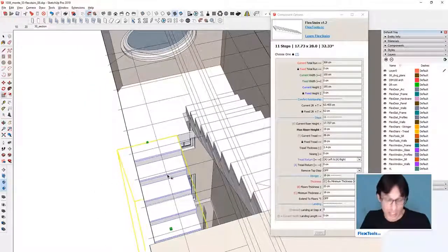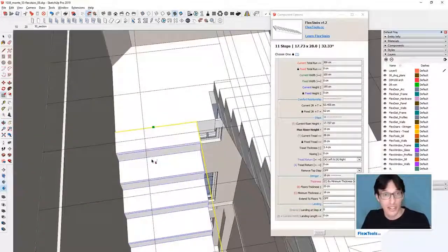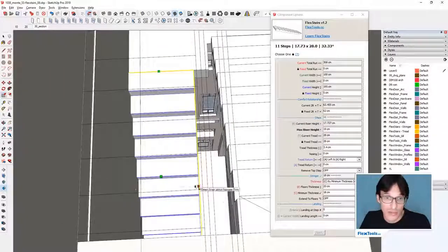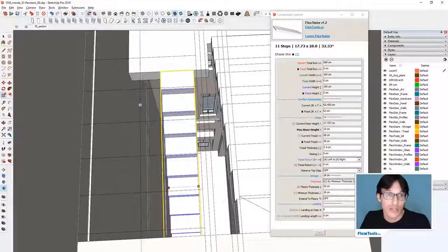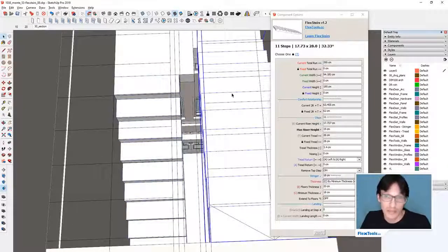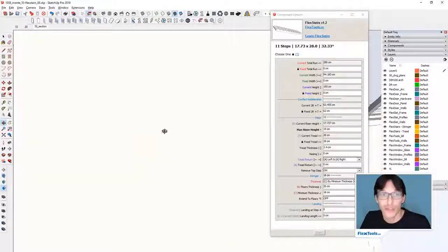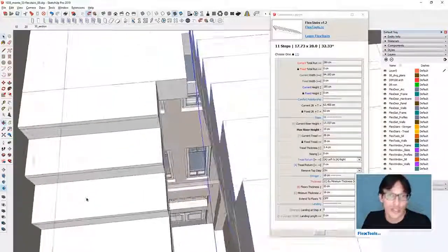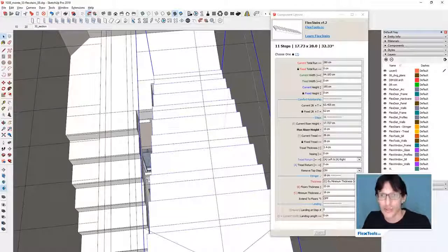These ones are placed okay, but they're probably not in the correct scale. So let's scale their width until they get to, there we go. Okay, width is 93.596. I guess that's what it turns out, 94. That's pretty good. Close enough. Of course, you can determine it exactly with the fixed settings. There are all the fixed settings here. You can just fix it at 94 if you want, and it's going to stay 94.